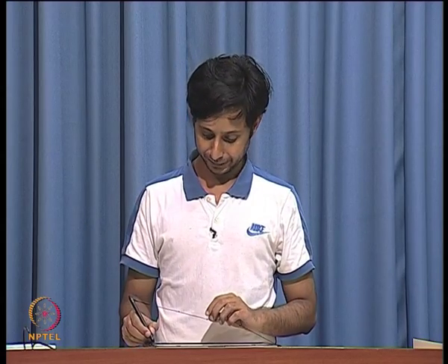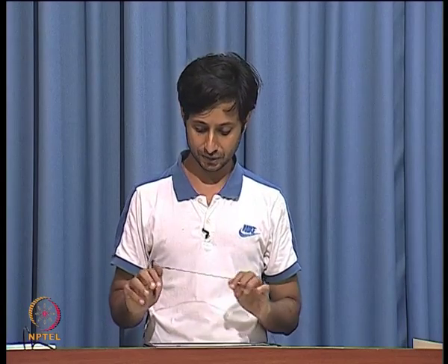Now, comes the question, why did I favor this particular network? The reason why I favored this network is because of parasitics. So, you might have heard of parasitic capacitances in earlier courses. Whenever you have two objects, there is a parasitic capacitance between these two objects, or whenever you have one object, you have a parasitic capacitance between that one object and the reference potential, that is ground, right.